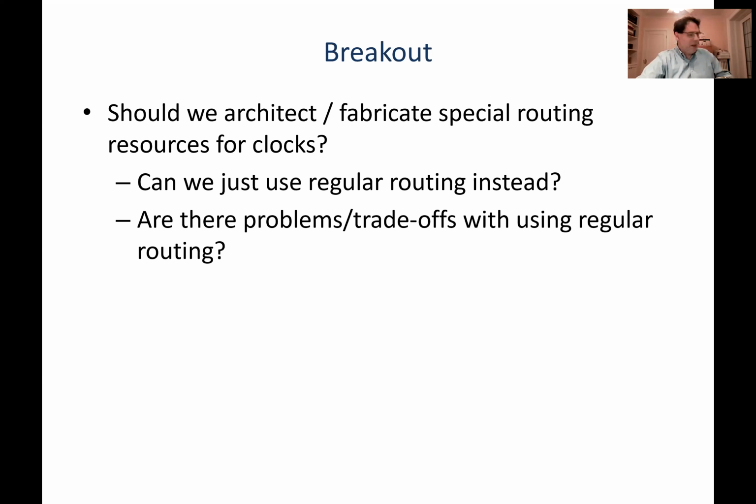So I want you to go in the breakout room, and we're going to start talking about how FPGAs distribute clock. So the key question I want you to think about and discuss is, do we need special routing resources for clocks? Should we build something special in our FPGA for clocks? The alternative is we just use regular routing.